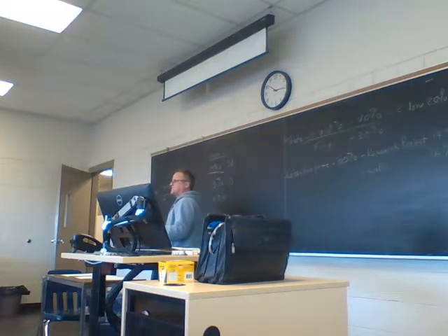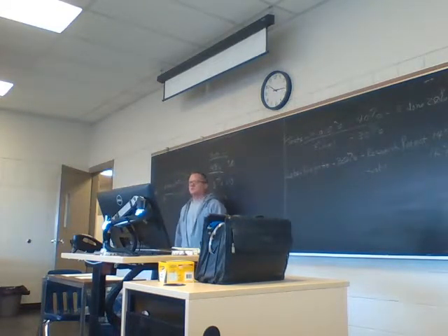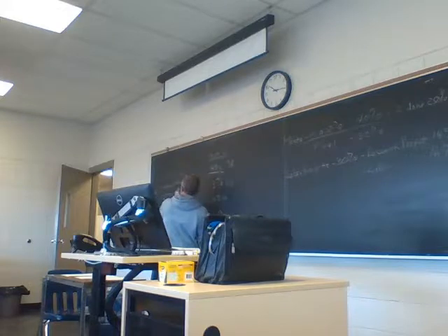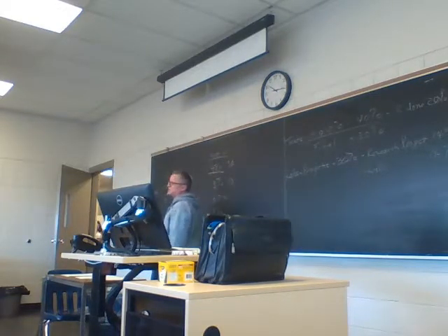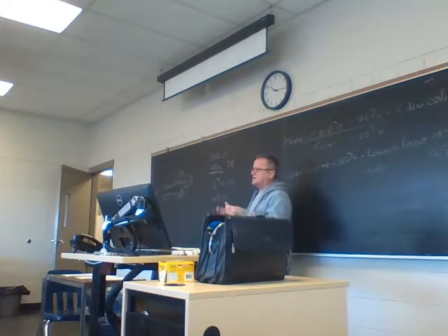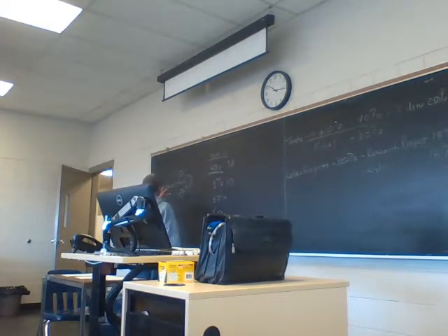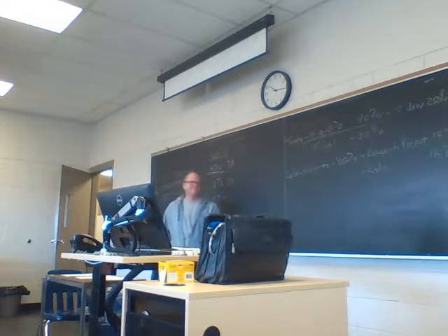And how does it see the difference between here and here? Current transformer. This current transformer sees how much current is going there, and a current transformer on that conductor sees how much current is going there. The circuitry inside is comparing those, and if it's set to a tolerance of 4 to 6 milliamps, it's going to open the circuit.